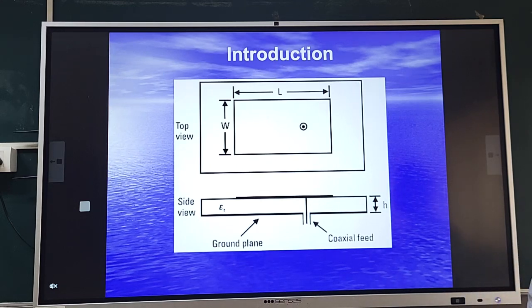Another variation we generally use in design: I personally prefer using FR4 substrate, but in the air suspended configuration. So I use a combination of air as well as FR4 substrate. In this process, I am using a low-cost substrate, but the air suspended design makes the composite substrate properties close to those of air.